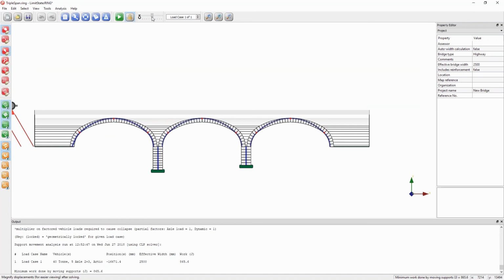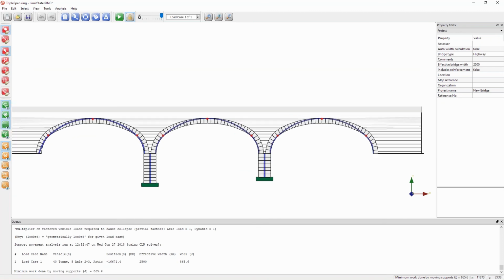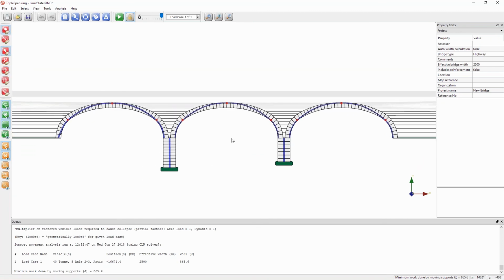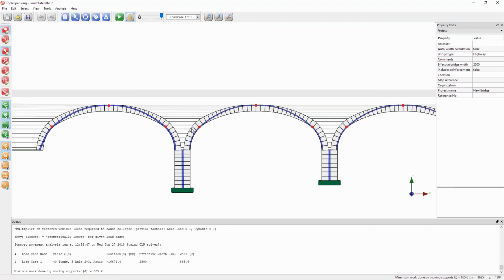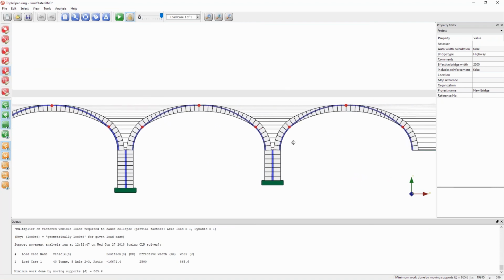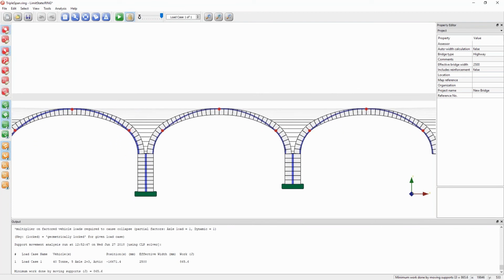I've actually got something that in terms of numerical calculation isn't that meaningful. I get a work. More useful is I get a mode of response. And you can see, hopefully, that I've got 3 hinges forming in each of these spans because I've effectively relaxed the spans, or gradually increased the distance between those supports.